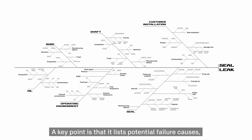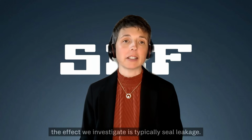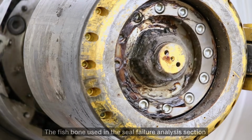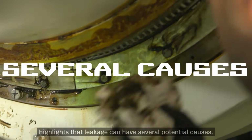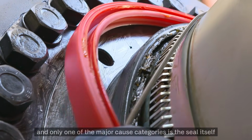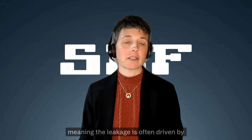A key point is that it lists potential failure causes and then we work through them systematically, one cause category at a time, checking evidence and ruling out what doesn't match the facts until the most likely root cause remains. In the SKF industrial shaft seal context, the effect we investigate is typically seal leakage. The fishbone used in the seal failure analysis section highlights that leakage can have several potential causes, and only one of the major cause categories is the seal itself, meaning the leakage is often driven by the system conditions around the seal.